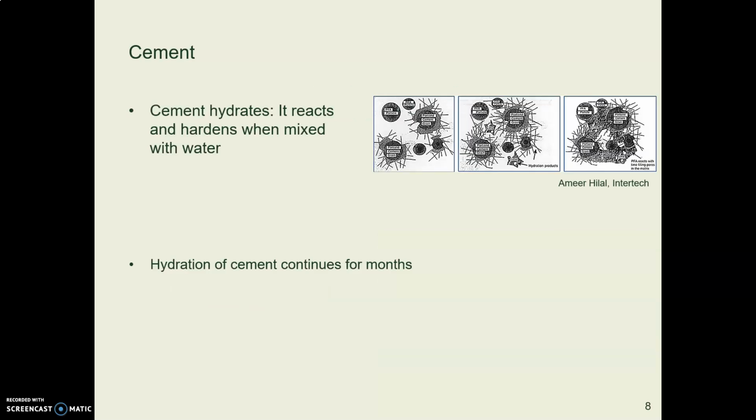What makes concrete get hard is that the cement, this powdered clay and limestone, has a chemical reaction when it's mixed with water, and that chemical reaction is called hydration. You notice that word hydro actually means water in Greek, and when we talk about we need to drink enough water, we say we want to be hydrated.